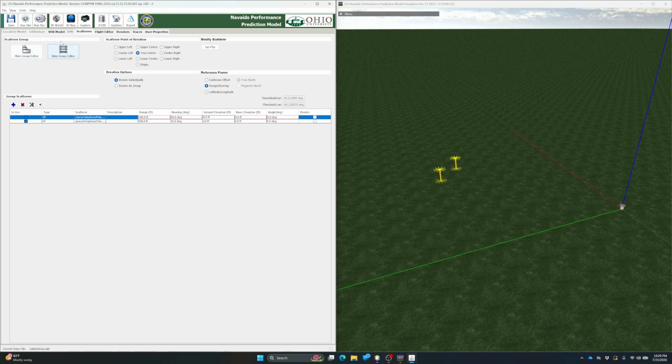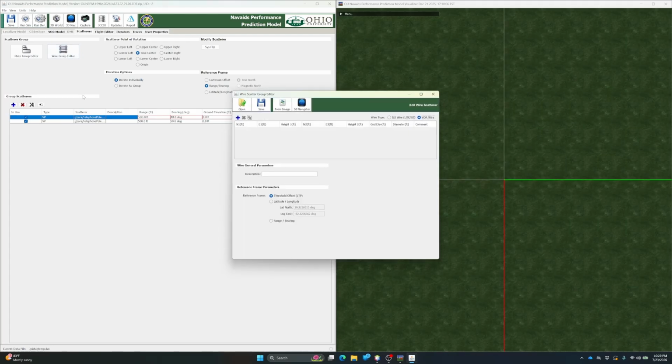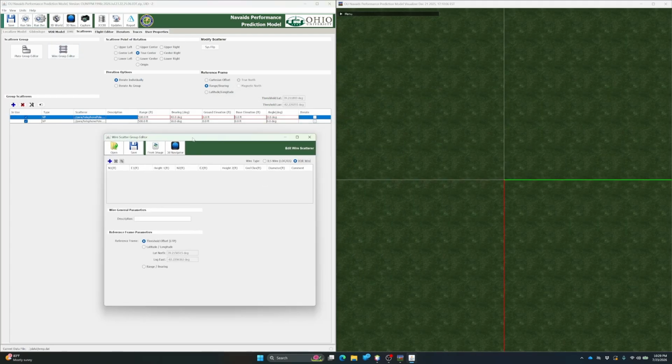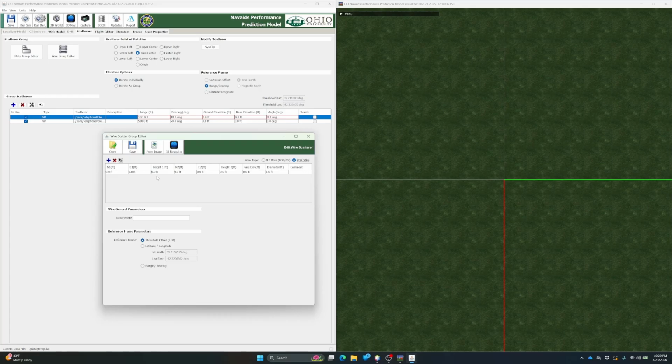You'll notice, in our 3-day training, we don't actually talk about wires very much, but we're going to make a wire here. There is a special rule that says that for wires, we don't recommend that the diameter of the wire be more than 1/10 of a wavelength.